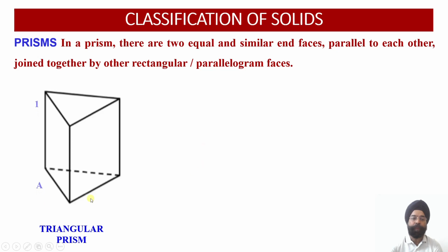So what we have to do, please see, every time we name any solid, we will name it this way. The lower or the upper corner of any vertical edge can be named as A and the opposite corner can be named as 1, so that we easily remember that A and 1 have to be joined over here. Similarly, the second point B will have the opposite corner named as 2 always. Similarly, the opposite corner of C will be named 3.